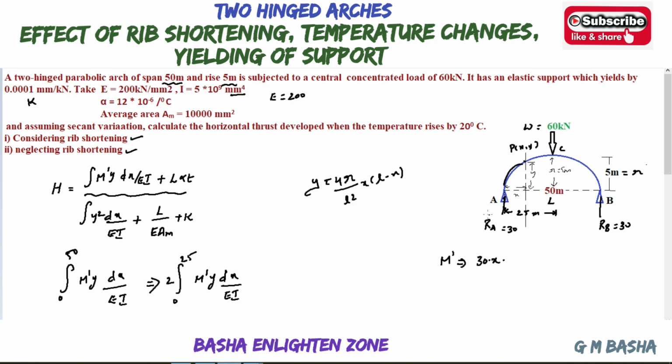See here, the values we are substituting are in terms of meters. So whatever the overall values given for the span, here the units are in mm. So please change these values into meters only. So that is 200 into 10 to the power of 6, kilonewton per meter square instead of kilonewton per mm square.